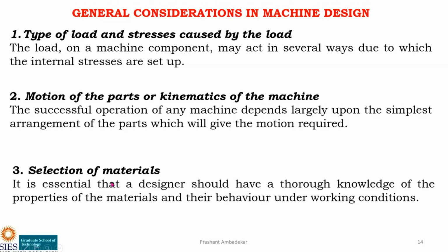Then next is selection of material. Once we know the stresses, once we know the load acting, we can select the various materials. Again, I told you in the earlier lecture that a particular purpose can be solved by 2, 3, 4 materials. Depends on what materials are available, we will select that material. Again, the cost factor is also involved in it. The working condition is also a deciding factor in selection of material. So based on all these factors, the material has to be selected.